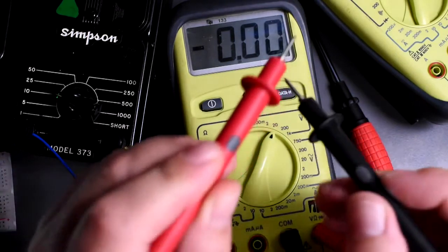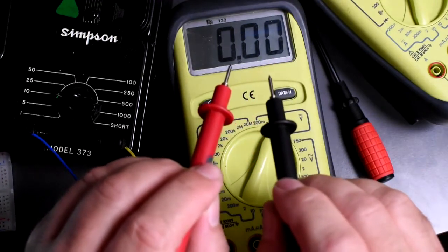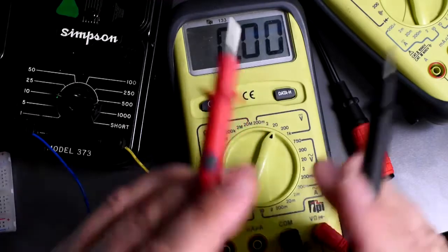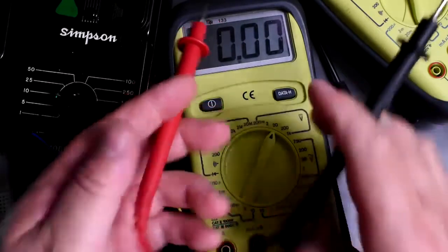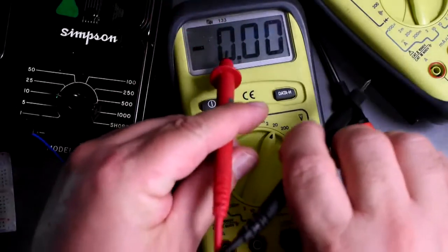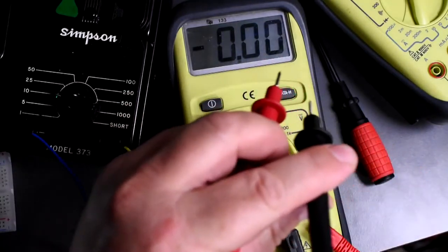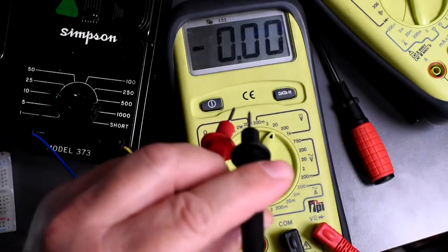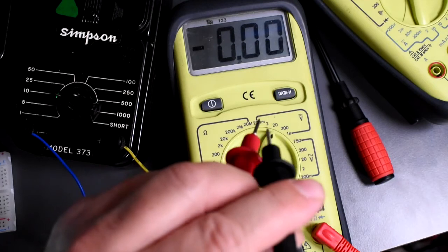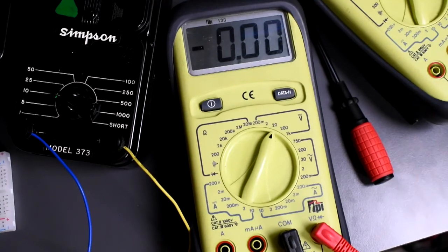So we could hold on to these probes. Now, if you're measuring higher voltage, try not to use both hands, because if there's any break, if something is damaged, maybe there could be damage in those leads here, and you're touching with your hands, then the current is going to go through you. It's just an extra safety. So if you were measuring that, just hold it with one hand. That's a technique of holding with one hand. And with the other hand, you just hold it in your pocket, or make sure that you're not going to touch anything else with your other hand, so the current doesn't go through you.